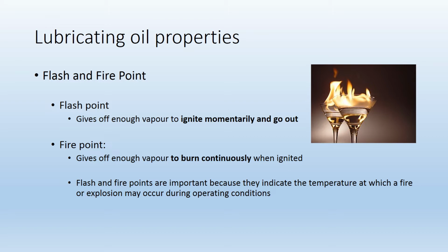The fire point is a temperature at which a liquid will give off enough vapor to burn continuously when it's ignited. The flash and the fire points are important because they will indicate the temperature at which a fire or an explosion may occur during operating conditions.